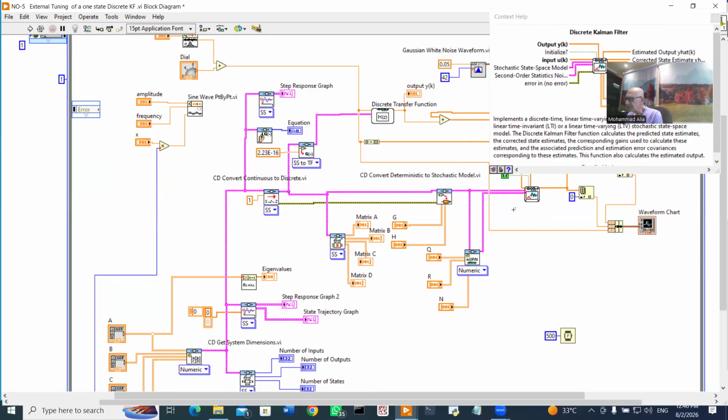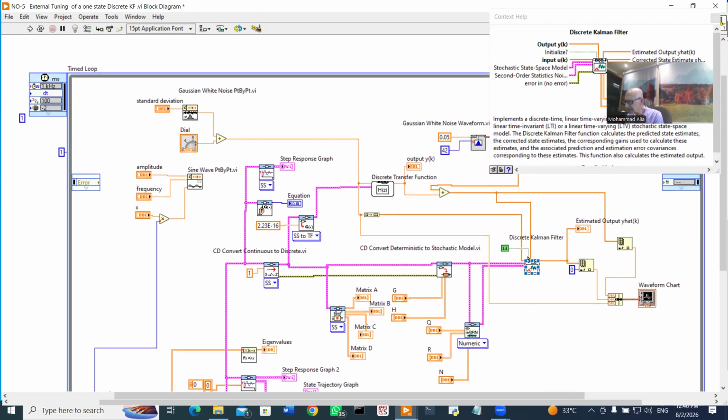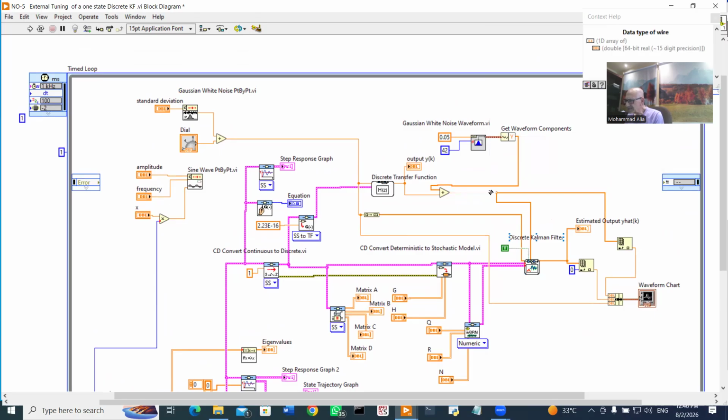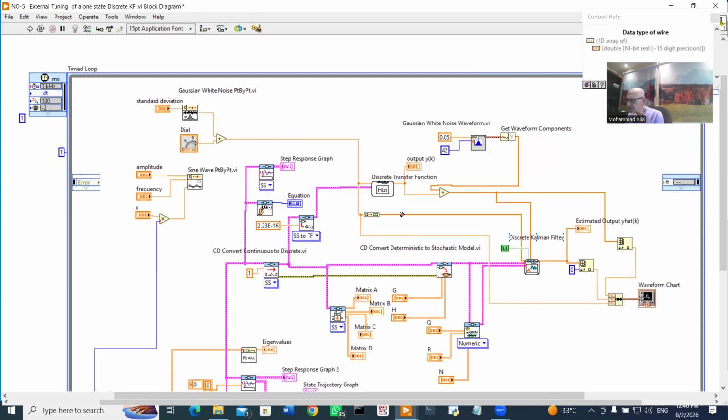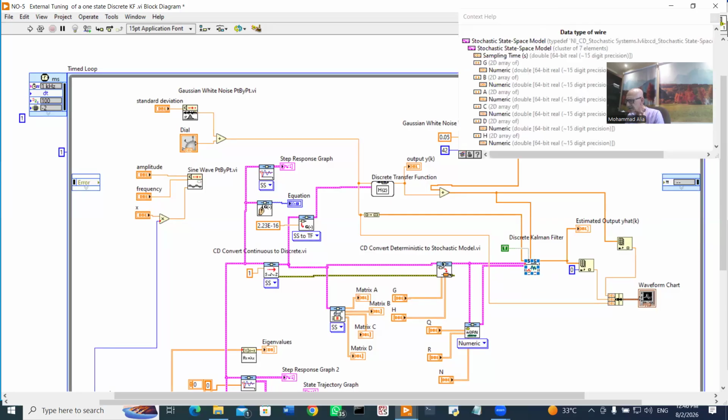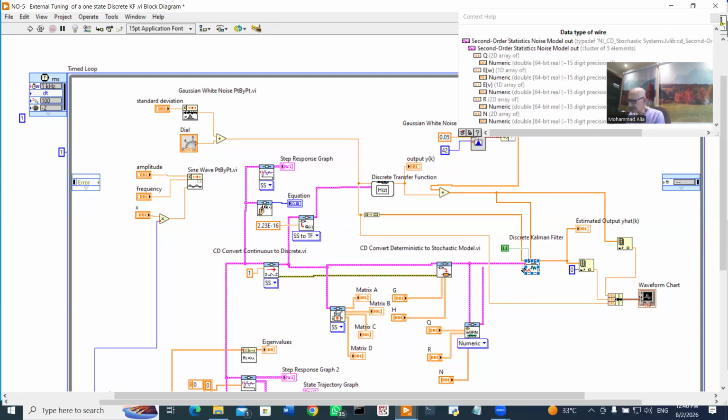and makes the reading more accurate. The feedback which comes as y of t, here is the feedback signal which comes from the system. Here it is simulated. The output, now I shall talk about it for you again. And the input u of t also, both of them are fed to Kalman filter, and now it gives an estimation. This estimation is very accurate, specifically when you have a stochastic state space model or stochastic system.